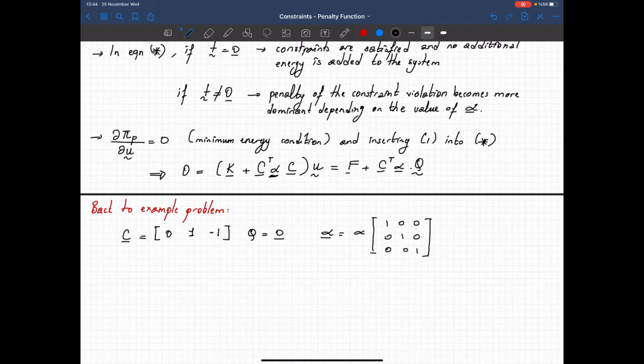Then I'm writing this equation now. I shouldn't be showing this way because I already play with that equation. Okay, I got K. K in our case is 2K minus K, 0, minus K, 2K minus K. That's the stiffness matrix.